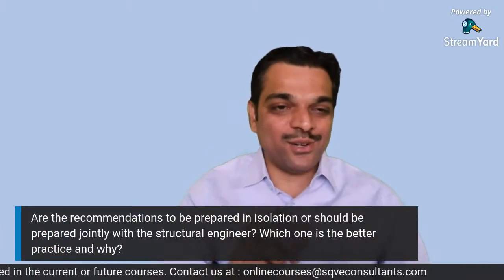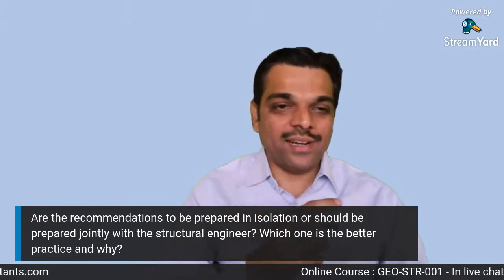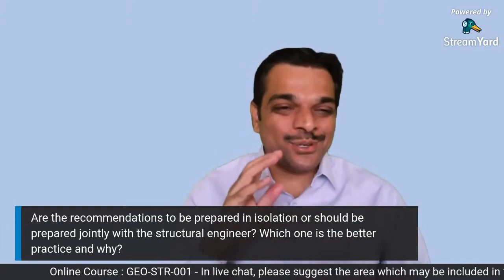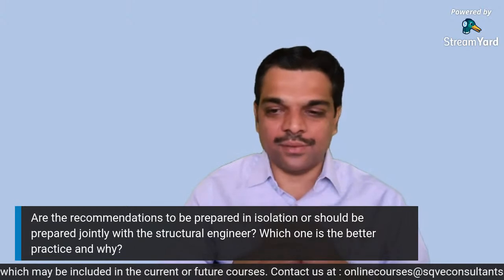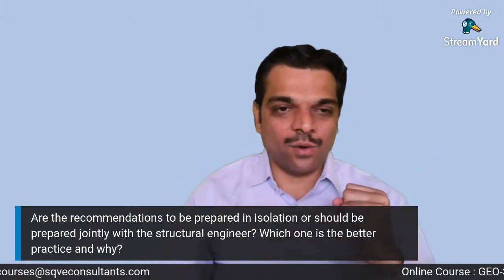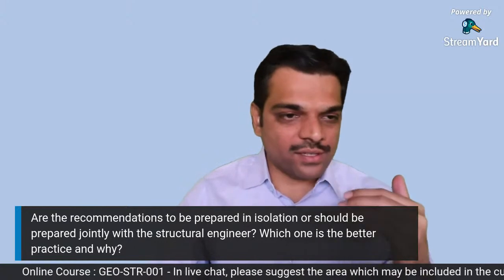Okay, this is a very interesting question. Are the recommendations to be prepared in isolation or should they be prepared jointly with the structural engineer? Which one is the better practice and why? In my opinion, the recommendations must be prepared in consultation with the structural engineer, because the structural engineer can guide the geotechnical engineer on what kind of loading, which loading intensity is there, what the special structures are, what are heavy structures, and what are light structures in the overall plan. So based on that, I think always the recommendations part.